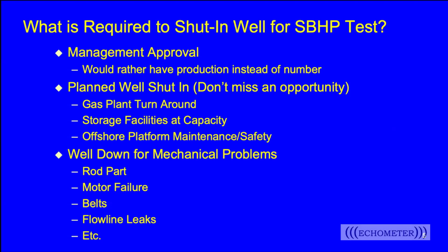I've worked in the field at times where there was a turnaround at the gas plant, and there was no place to go with the gas, so the entire field was shut in. That is an ideal case to get static bottom hole pressure. Today, we might see a lot of storage facilities at capacity, and we're having to shut in wells because storage is at capacity. Again, that's an opportunity that we shouldn't miss. Perhaps if you're working offshore, there might be some maintenance or other considerations going on on the platform that shut that well in.